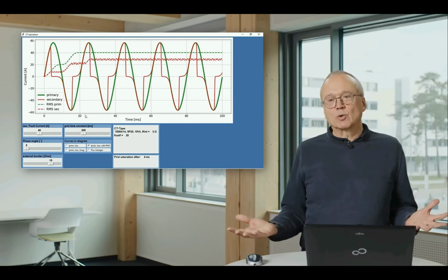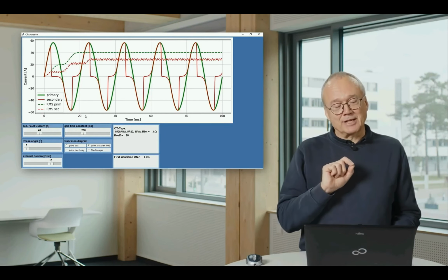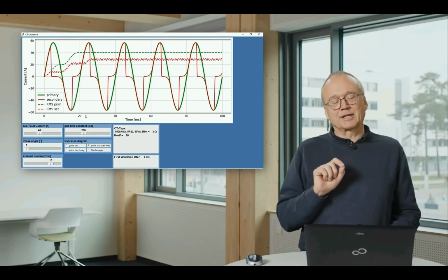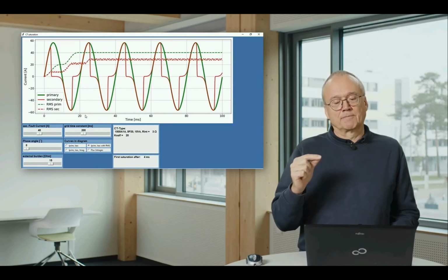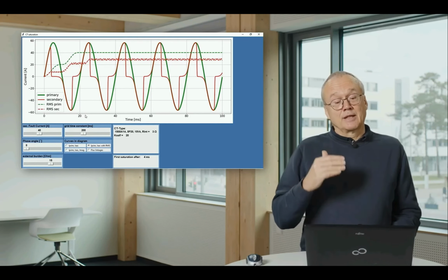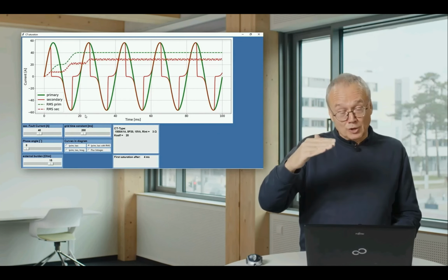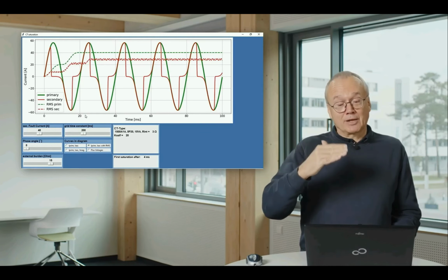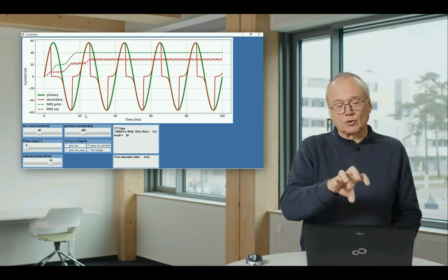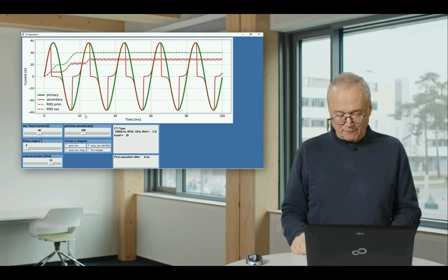In this case, the relay would trip, and this type of saturation doesn't disturb us. But if we would have a setting, which is not really a realistic case, of 35 amps, then the current is 40 amps, the setting is 35 amps, so we would expect a tripping, but what we calculate from the disturbed curve is only 30 amps, and in this case we would have a missing trip.